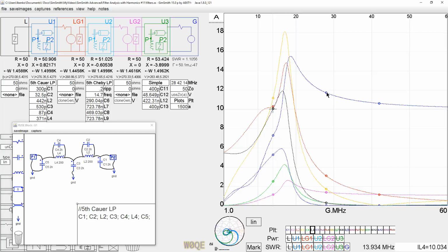And we don't care what the current is out here because you're never going to actually produce 1500 watts at 28 megahertz. So that's all we really are looking for is in this area right here, because that's where we intend to be using this. We will have a signal here, but it'll be 20 dB down, and the fact that it's 20 dB down from 12 amps is a tenth of the current, so it'd be 1.2 amps. So these numbers aren't too important.